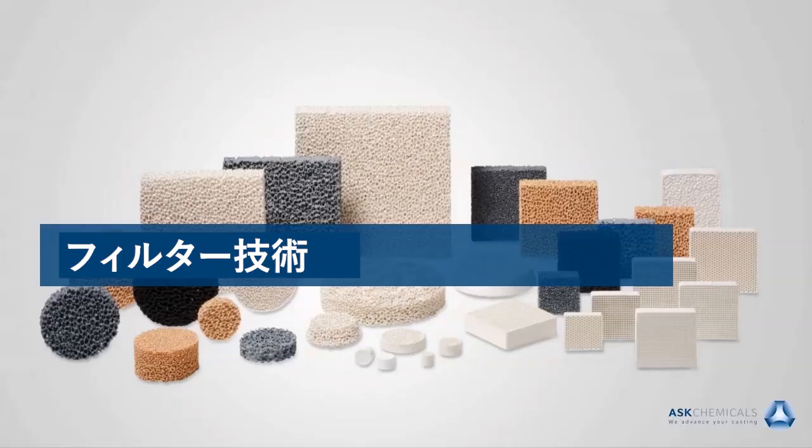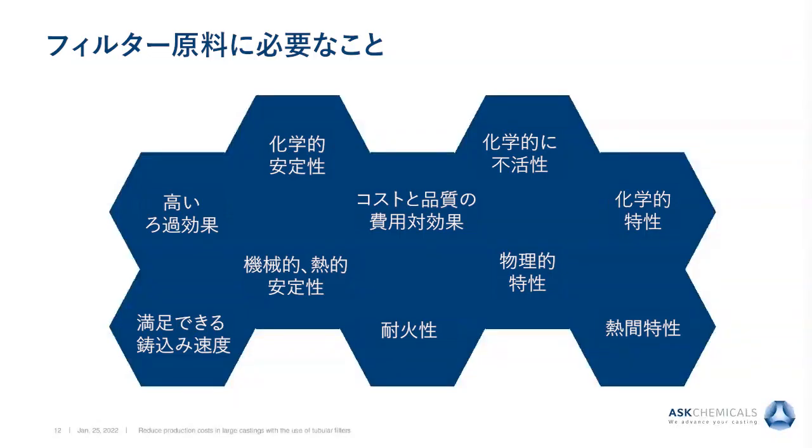Let us now switch over to some basics of the technology of ceramic foam filters. Because of the typical application, that means molten metal at high temperatures and pressure at least, there are some very important requirements which the filter material must fulfill. You can see it here on this slide. You need a chemically stable material, mostly chemically inert. It must be, of course, mechanically and thermally stable, and it must also have a high refractoriness. Good thermal properties are also very important.